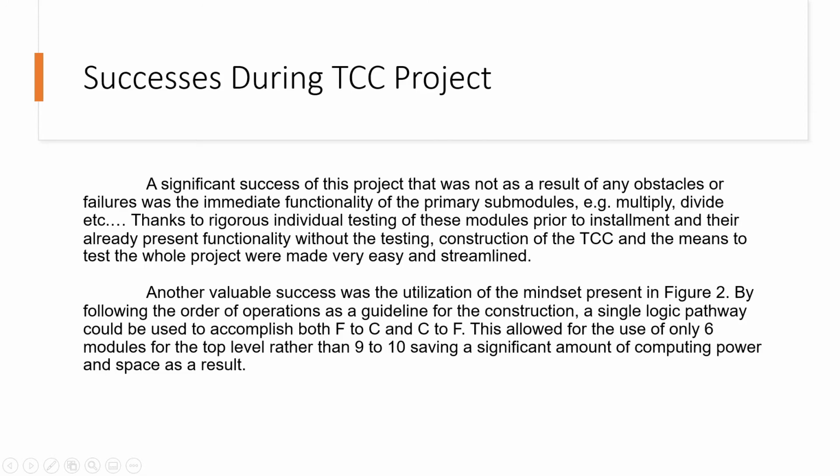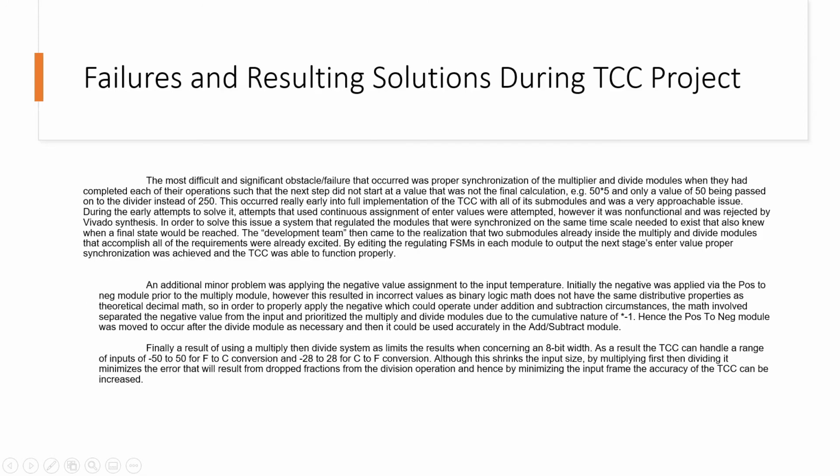Now we move on to failures and the resulting solutions from those failures. The most difficult issue that I encountered while creating the TCC was proper synchronization of the multiply and divide modules. My biggest issue was that I could not properly synchronize the end of one with the start of the other initially. I attempted to use continuous assignment to solve that issue, but not only did it not work, it was also rejected by the Vivado synthesis function, making it utterly useless.